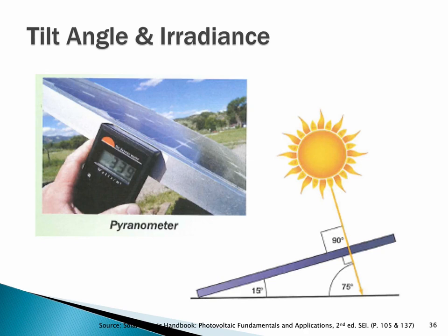So as we saw with the PV watts, the tilt angle changes output, and orientation, the azimuth, changes performance as well. So we've already seen that.